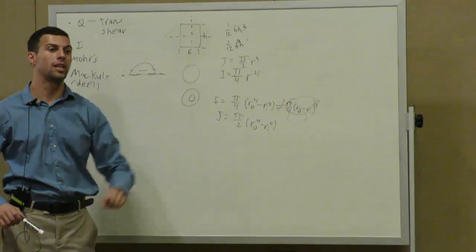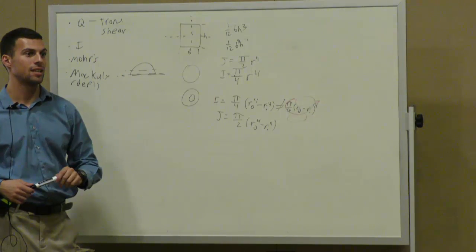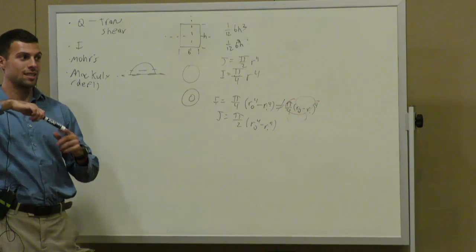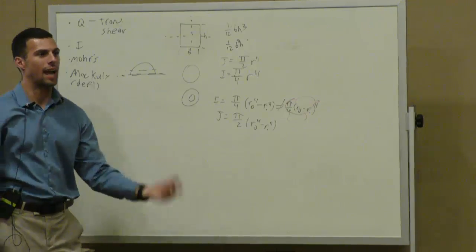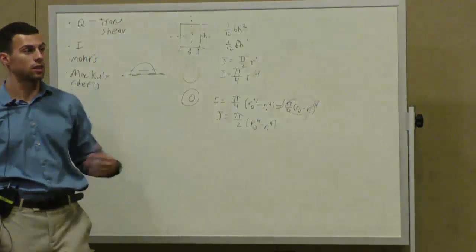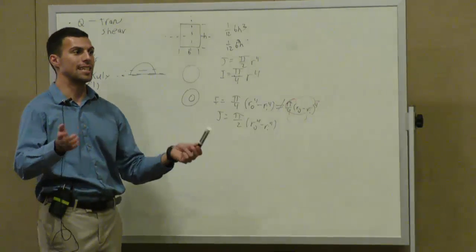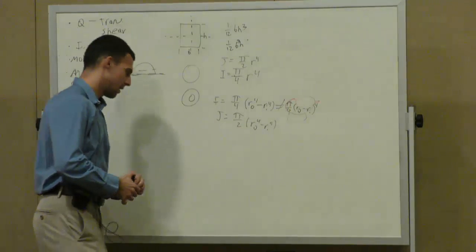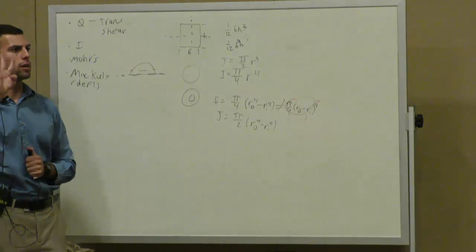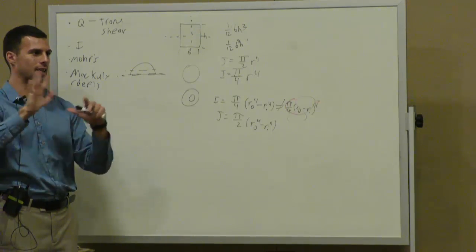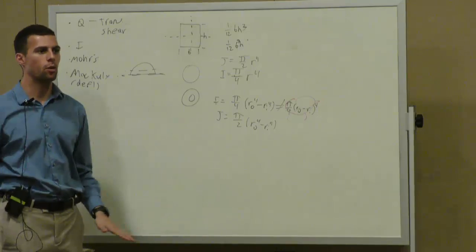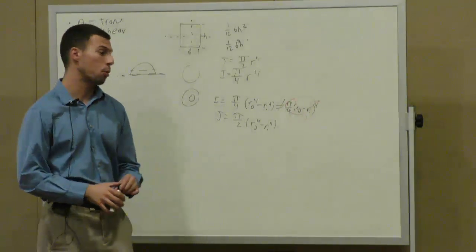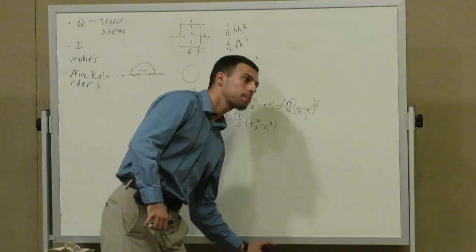Right, which is which load condition? TC over J is correct, and it relates to a load condition. What load condition? What is the T? Torque, right? It's torsional shear stress. Are we all familiar with the 4 load conditions? When I say that, does everybody know what I'm talking about? Awesome. Let's go over those, because those are really important, especially for combined loading.